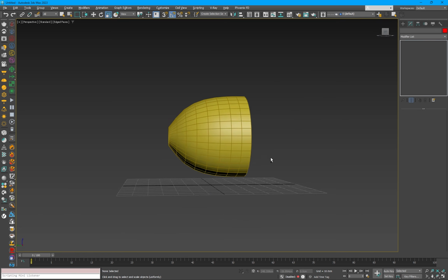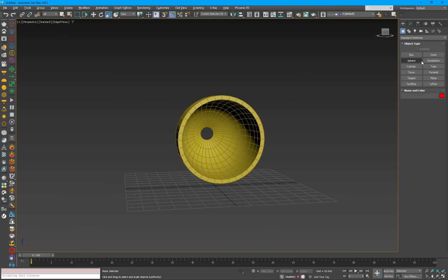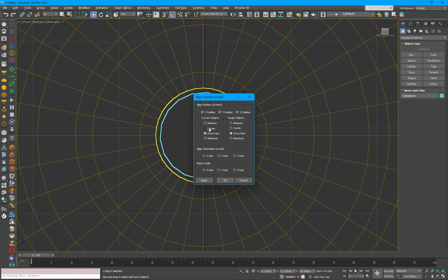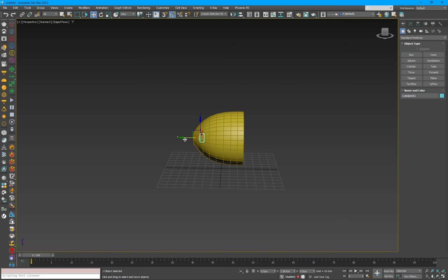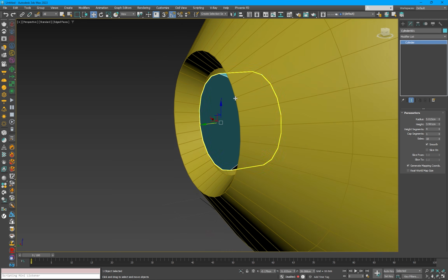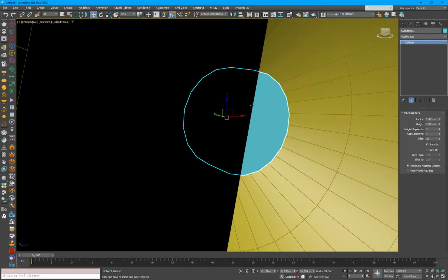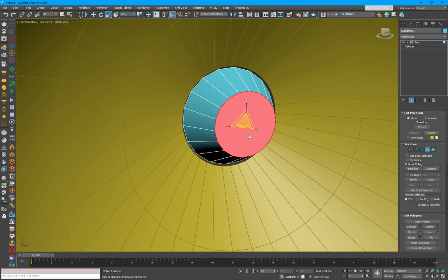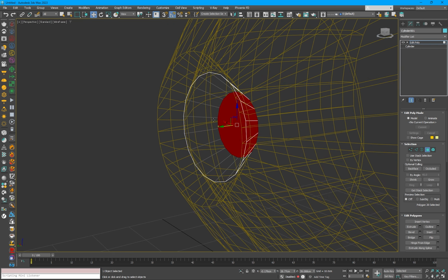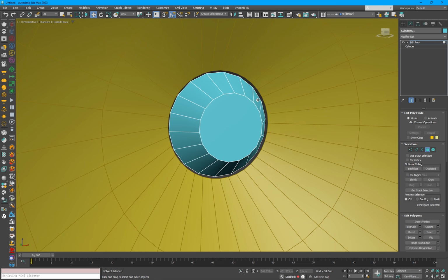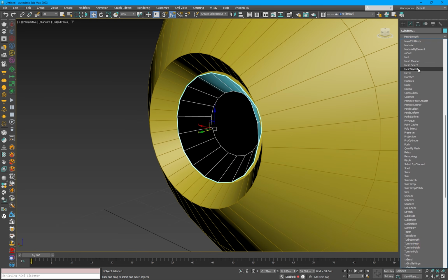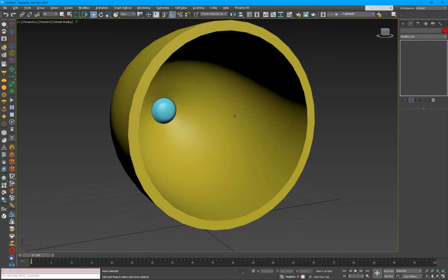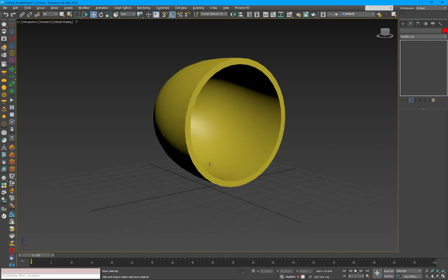The second geometry we need is an emitter object to emit our temperature. I'm using this basic cylinder object. You just need to place it in the middle of the hole in the nozzle. We don't need too many polygons, but we need to adjust the shape. We can taper the top side and delete the back polygon, because we don't want to spray our voxels from the back. Also we can mesh smooth it, something like this.